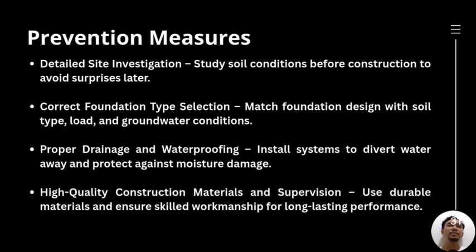We can do some things to prevent those foundation issues like detailed site investigation, correct foundation type selection, proper drainage and waterproofing, and high quality construction materials and supervision. First is the detailed site investigation. We need to study the soil conditions before construction to avoid surprises later.